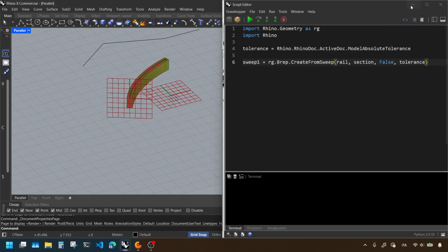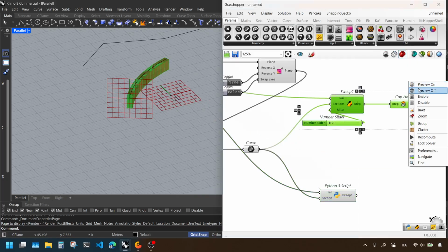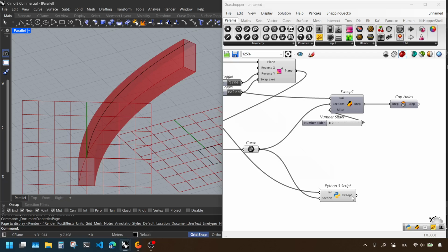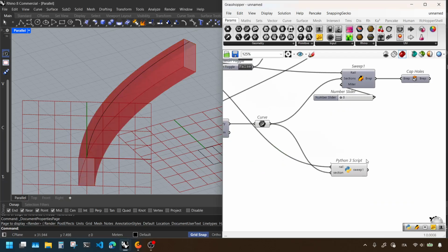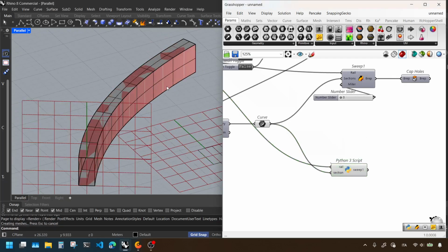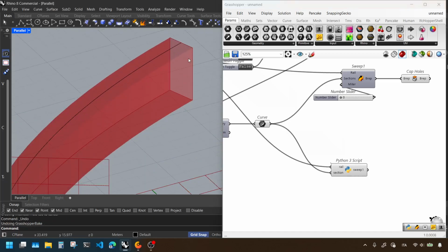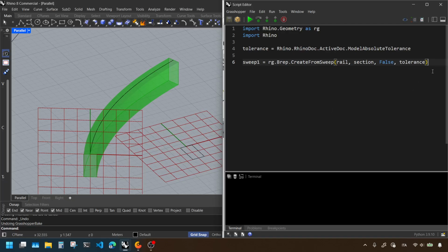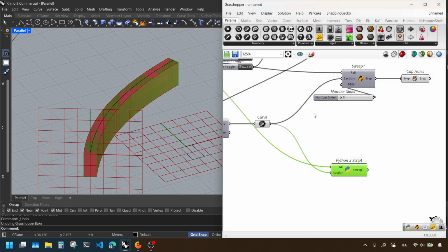And indeed, you can see from the greenish color that it's the same exact result. And we have now made a Brep as an untrimmed surface. You could bake this as well, and you see it's exactly the same. There may be something weird with the visualization because when you create Breps, you can actually fix the vertices, but we'll see this in a future episode when we discuss previews, because this creates problems with previews when you create plugins. So let's not see it right now. Okay, so this was sweep 1.